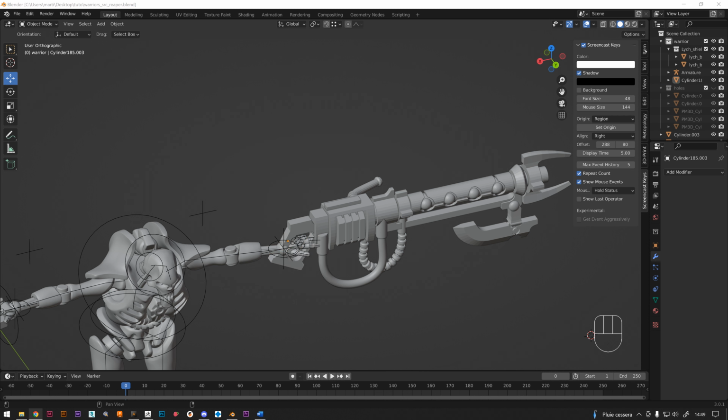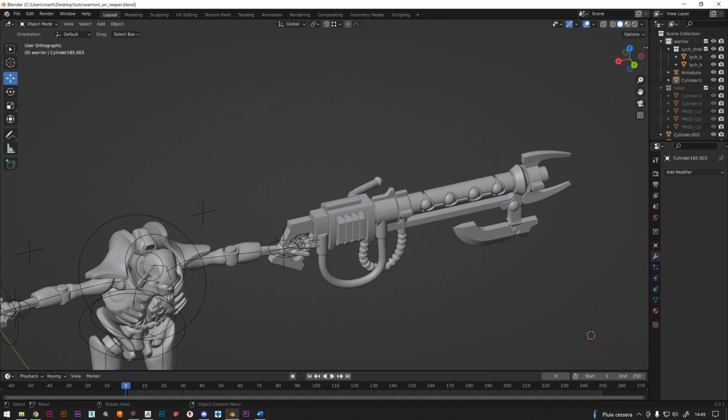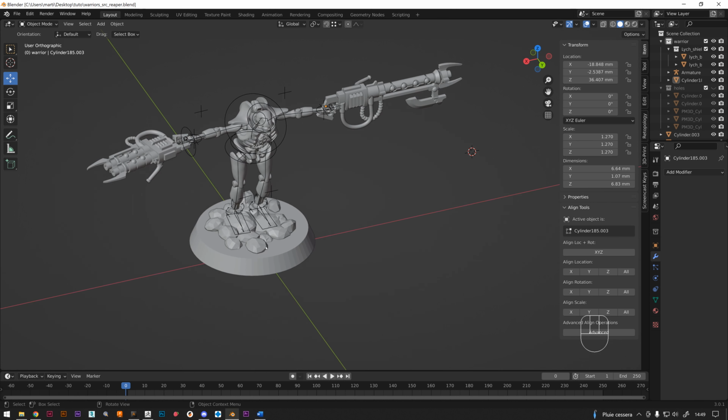In this panel, in the Item tab, just before, let me tell you that like the left panel, this panel can disappear if you accidentally press the N key, so you can make it reappear either with the N key or by grabbing it like that. So we have a panel called Transform, and here we can see the X, Y, and Z location values of the selected object. These coordinates are absolute, that is to say, relative to the center of the world, which is represented here, under the base where the three axes are crossing each other.